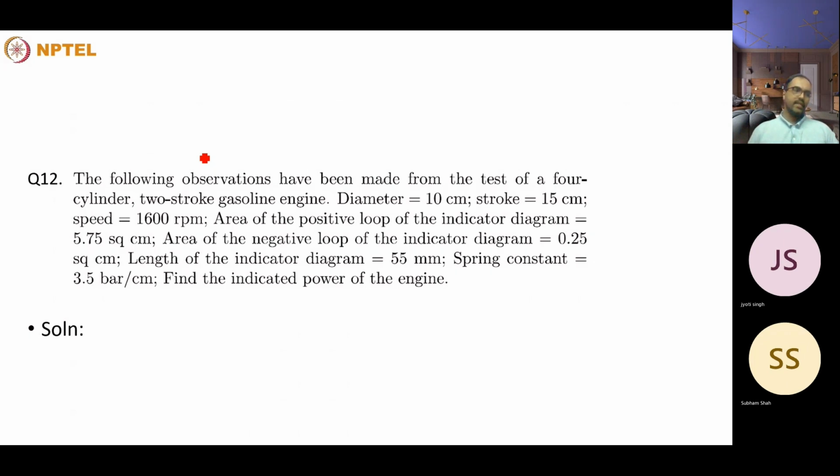This is a question regarding engine performance and characteristics. By taking the area of the indicated diagram, we can calculate the indicated power. So that is another way of calculating the indicated power from the graph, apart from the normal ways of calculating it based on the brake thermal power as well as the frictional power. We can calculate the indicated power using this method as well.